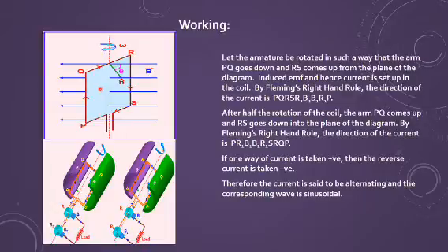These two should be perpendicular to each other. Then you have to rotate the coil around its axis, which is perpendicular to the magnetic field, and I can get the direction of the current by using the right hand rule. So for every arm you can find the direction of the current simply by the right hand rule.